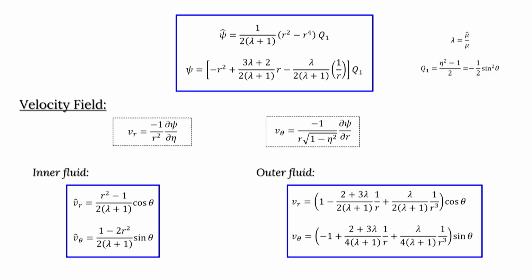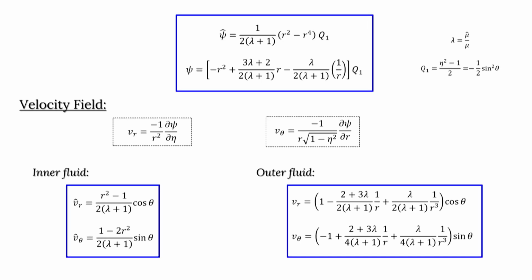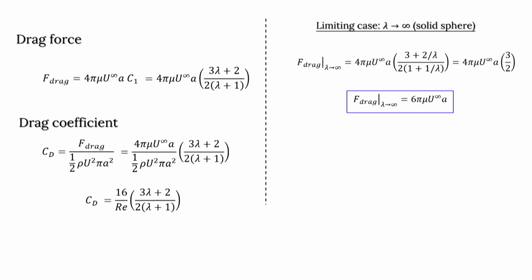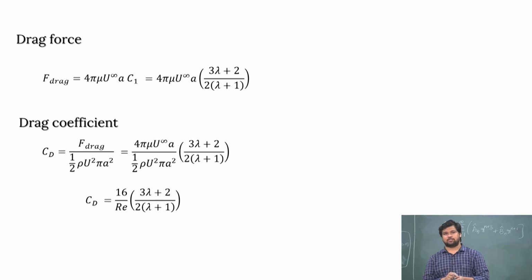You can actually validate these equations also. You have boundary conditions, right? You should always validate your solution, because you got some solution, and it might be right, it might not be right. Always check with your boundary conditions, whether the boundary conditions are satisfied by Vr and V theta or not. And one more thing, the continuity equation also you can try to verify. And similarly, for calculating drag force, I am simply saying this is the drag force and drag coefficient. So from here you can show that.